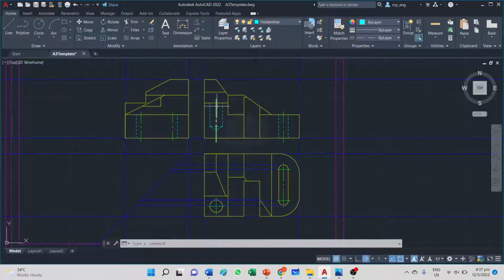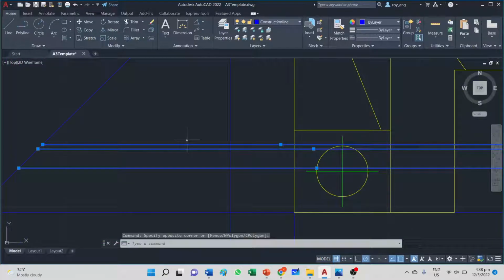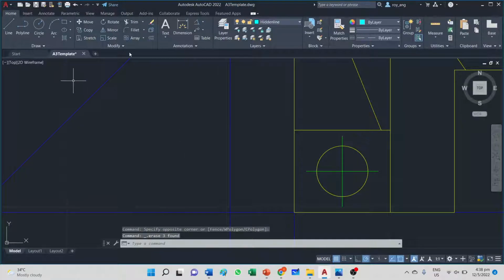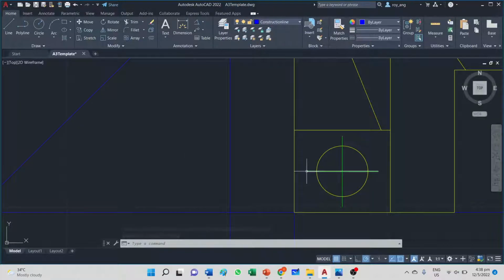And I'm going to ask myself, where is the position of my drill hole? It's somewhere around here. Okay, and I am going to delete away all this because it's going to be very messy. Alright, and I will draw the center line of the center. I'm going to project the center line of the drill hole. Okay, and it must hit the 45-degree mitre line.